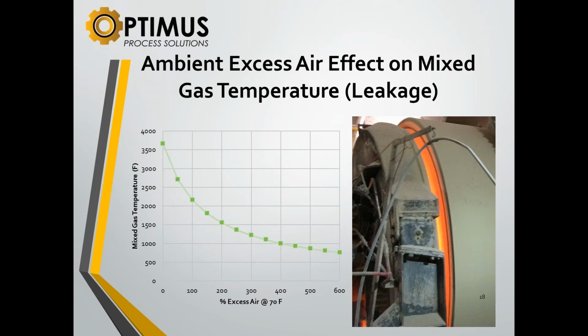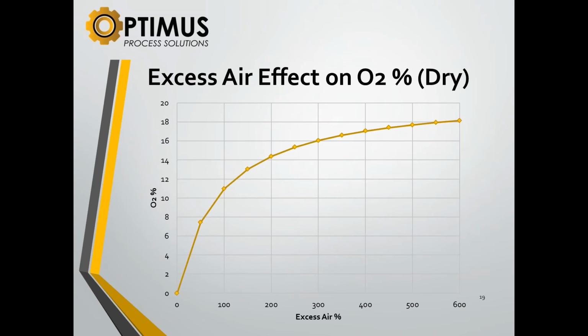Now, one thing that we measure, we have an analyzer you can buy. You measure the O2 coming out of your kiln on a dry basis, not a wet basis. Dry meaning no moisture in there. It doesn't consider the moisture, and most portable ones are dry basis. As you increase the air above stoichiometric, the oxygen level goes up. Most kilns are operating down around 1 to 2%.